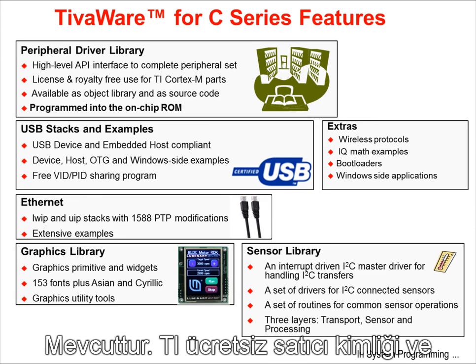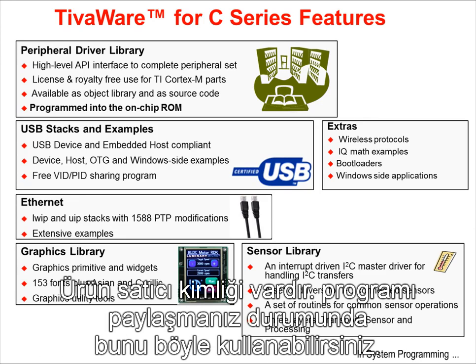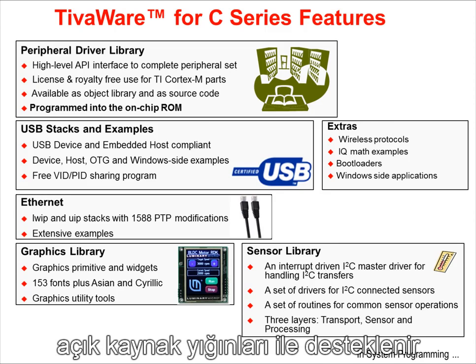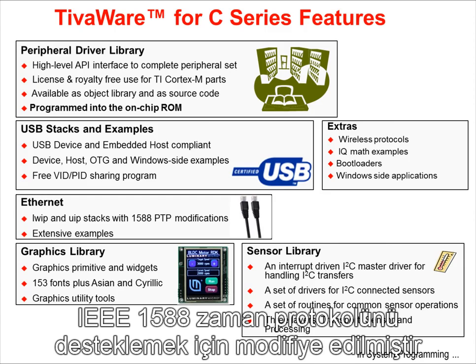TI has a free vendor ID, product ID sharing program should you wish to use it. Ethernet is supported with lightweight IP and micro IP open source stacks. Both stacks have been modified to support the IEEE 1588 Precision Time Protocol.